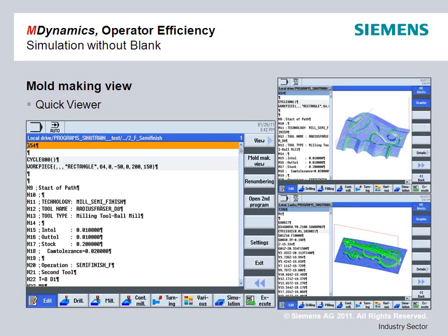Especially for the aerospace guys, where the stock material you're starting with is not a nice, easy rectangular or cylindrical part. It's probably some piece that's been partially roughed already, or some kind of complex composite that you're trimming. This will at least let you see that, yes, that looks like the part I'm going to be making, and there are no strange G0 moves right into my table. These simulations can run very quickly on part programs with high density points. While it's not as good as something like the VeriCut analysis that many of you do, it's enough for the operator to make sure the paperwork I have matches the software that they gave me.